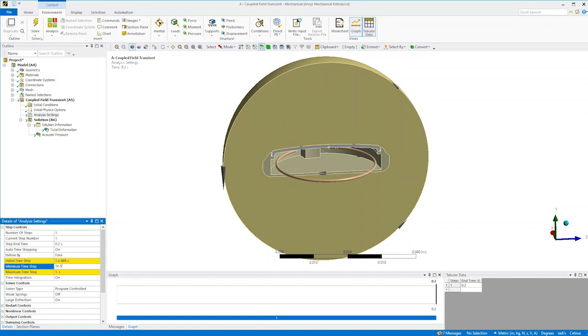Time stepping controls are required for this transient vibroacoustic analysis to sample at a high enough rate. The analysis is kept linear here, but could be nonlinear as well.